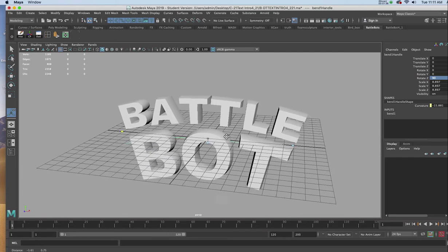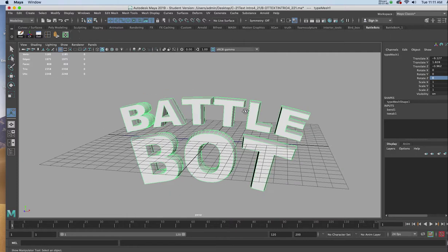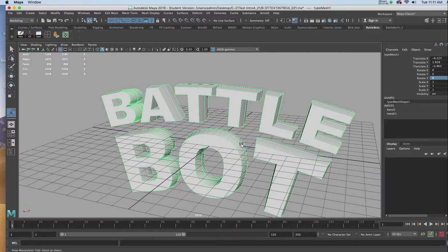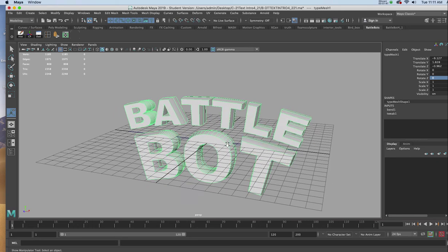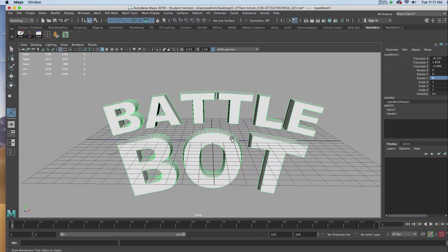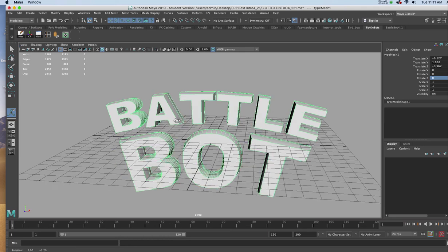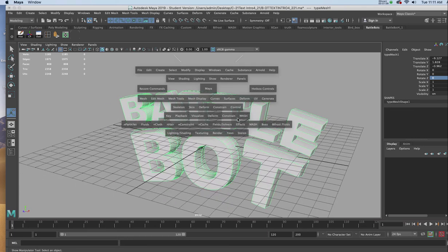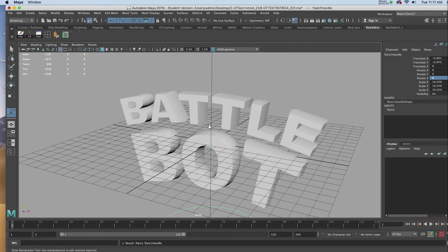Now, the thing you want to remember with this is that once you've got something bent in a fashion you want, and you want to add another deformer, you've got to duplicate it, or you've got to delete by type history. One or the other will give you a permanent bend to your geometry. So I'll go ahead and click on delete by type history, and then hold down my space bar, go to deformer again, and I'll go to nonlinear, and I'm going to choose flare.